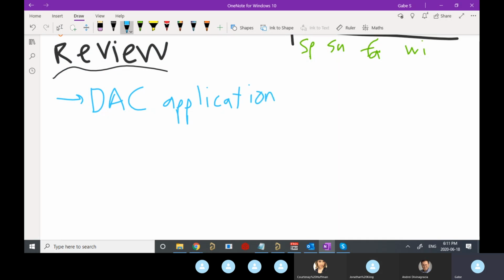So last week, we looked at applications of digital to analog converters and how you can have some control over physical systems with your microcontroller. There are a ton more, and we've mentioned a few that are in our car as well, specifically for that torque path from the foot pedal through to the VCU and then out to the Curtis inverter, where we emulate a 0 to 5 volt analog signal with a DAC that's on the VCU.